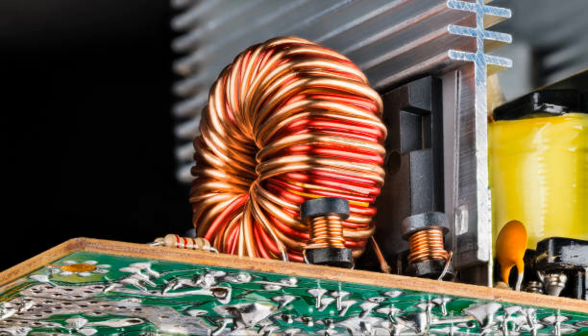2. Role of the core. Core material. The core of an inductor, particularly when made of ferrite, plays a crucial role in concentrating magnetic flux. Ferrite is a material with high magnetic permeability, which enhances its ability to channel and focus the magnetic field lines generated by the current flowing through the coil.